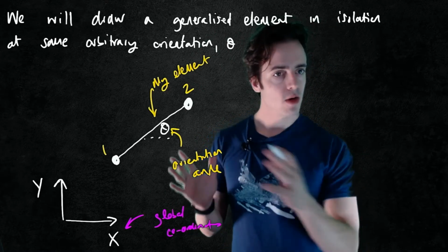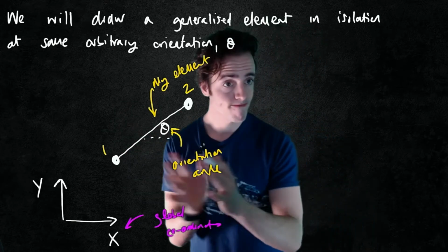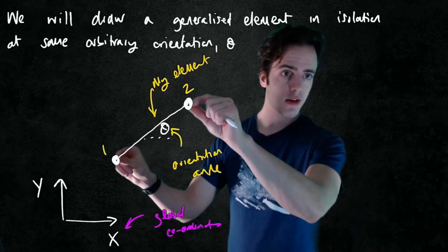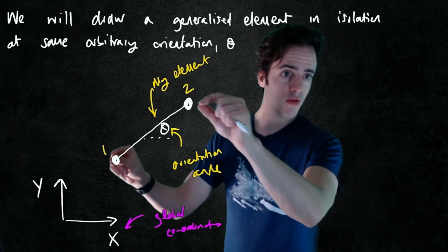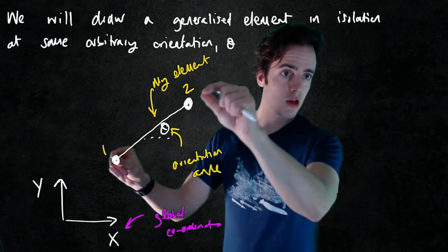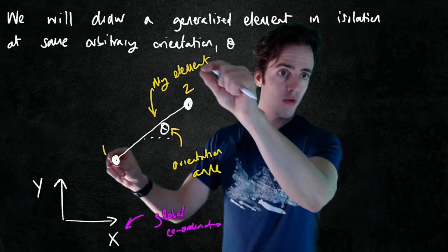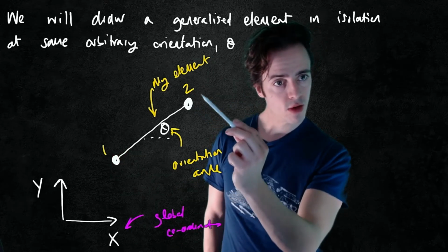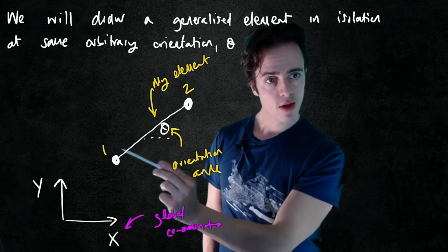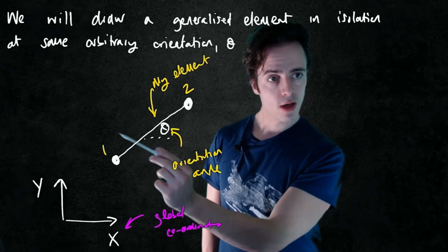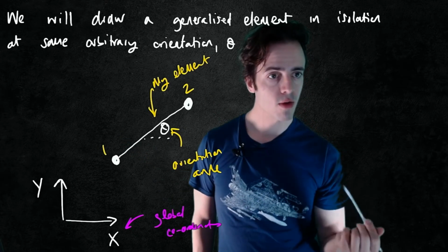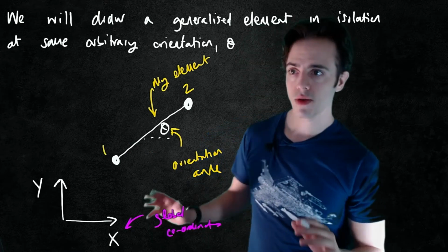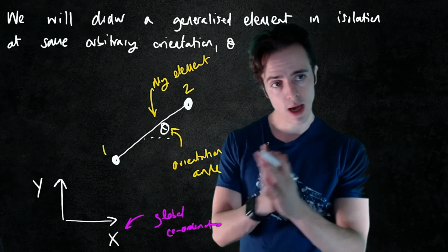So let's think about if this were in a structure, it could be deformed, it's going to extend, and it might sort of, each node could move both along the axis and could also move normal to its principal axis. So this node could move along and up. This node could also move along and up. So we give those two displacements, we give them symbols u and v.